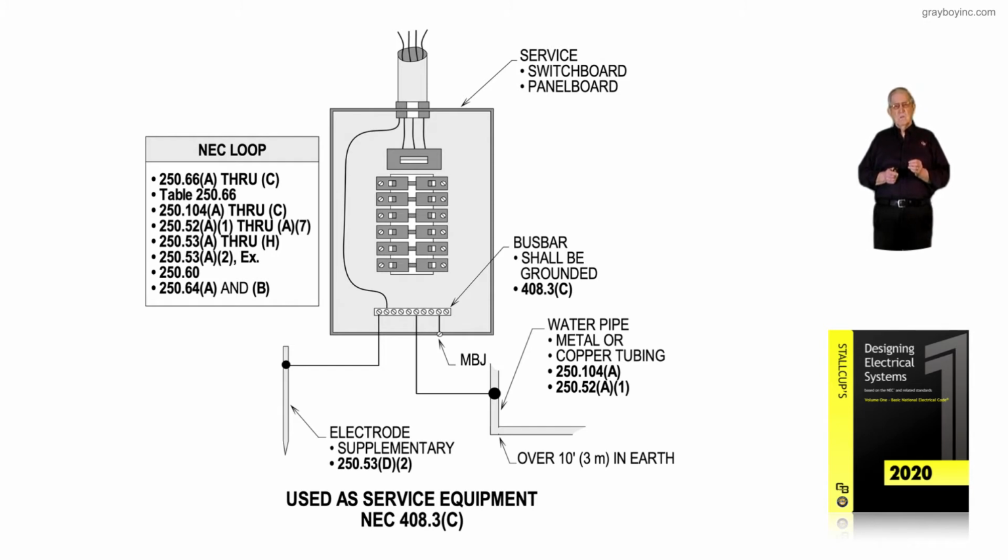That conductor is a grounded conductor to provide a path for fault current to travel over. Notice that conductor would be sized from Table 250.102(C)(1), and it too would be number 2 based upon that table, selecting number 2 based upon the 4/0 conductors. Notice two tables are used, but the conductors are all the same size.